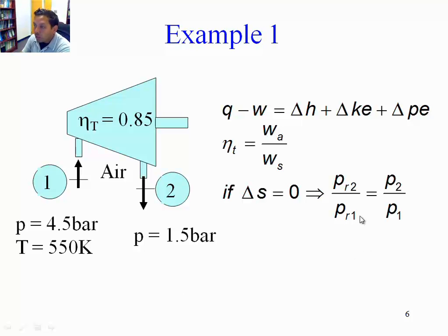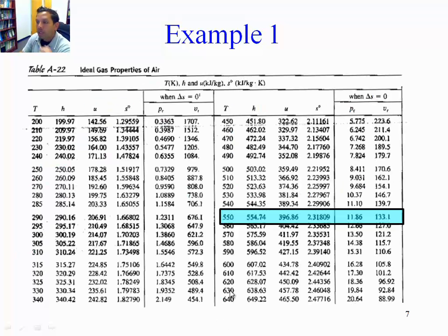And if we do so in order to calculate the ideal conditions at the outlet, because ideally the change in entropy from inlet to outlet will be 0, but in reality it won't because there's an adiabatic efficiency. So let's see. So we go to a table, ideal gas, since we're operating under the variable specific heat model. We cannot say that the delta H is equal to Cp delta T. We just go to a table with the temperature and find the enthalpy.